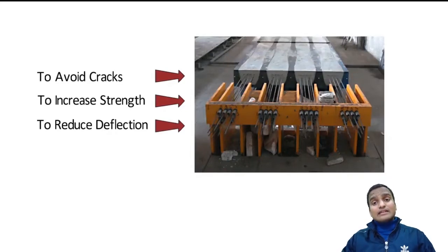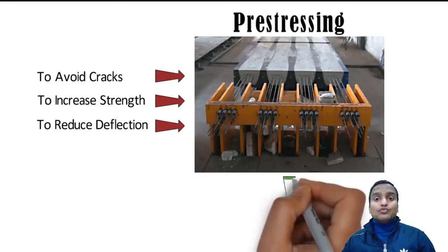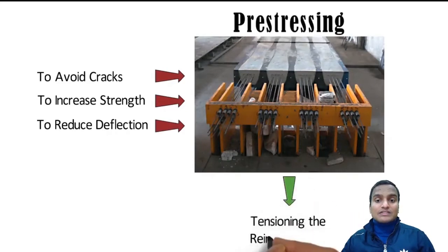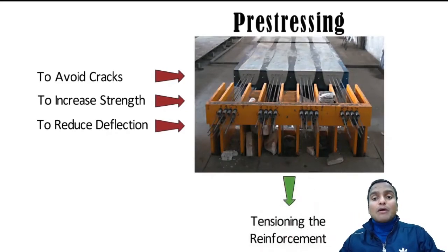And these tendons or steel reinforcement are anchored here with a certain mechanism as shown here, and they are jacked here in the anchorages, and there they are applied with certain stresses. So here we do the pre-stressing, as the name suggests, that we are already tensioning the reinforcement beforehand only. Okay. So when we go for the tensioning of reinforcement, such a concrete will be called pre-stressed concrete.